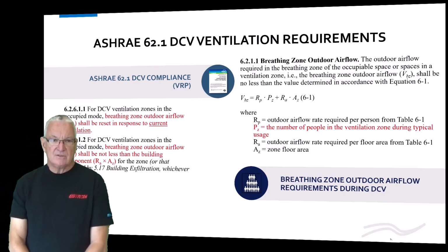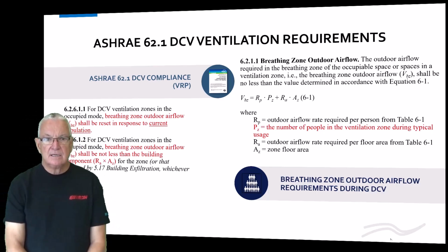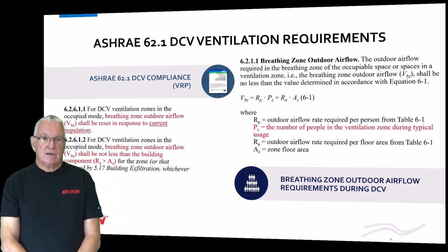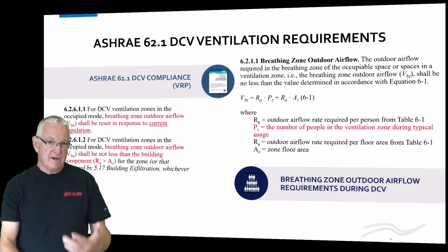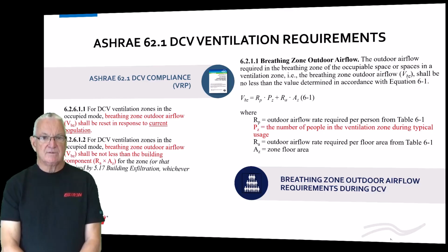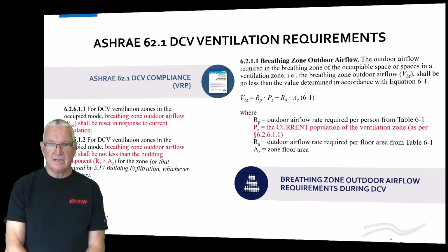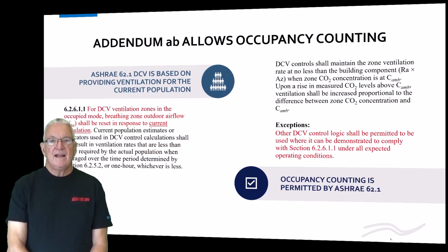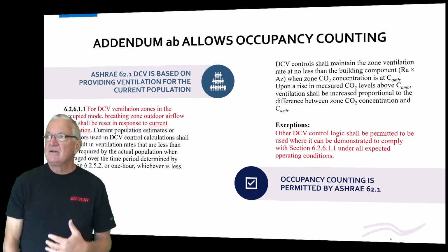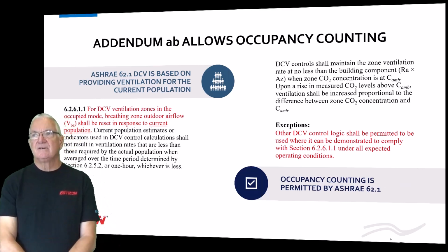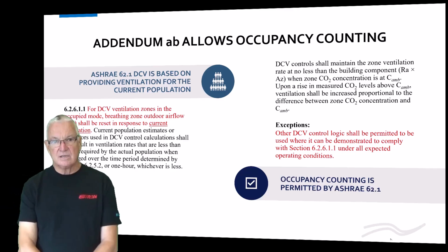Now, when we go back and look at this again, we've already looked at these slides. It's just a reminder that this language is still there. Breathing zone outdoor airflow shall be reset in response to current population, and you know what that means. So that allows us to get our heads outside of the CO2 thing if we want to.